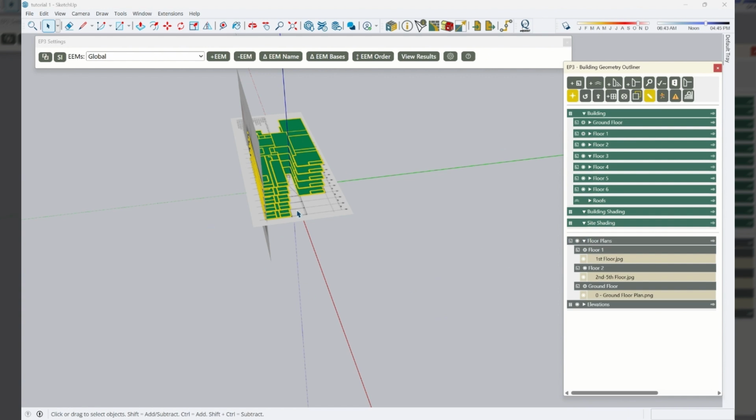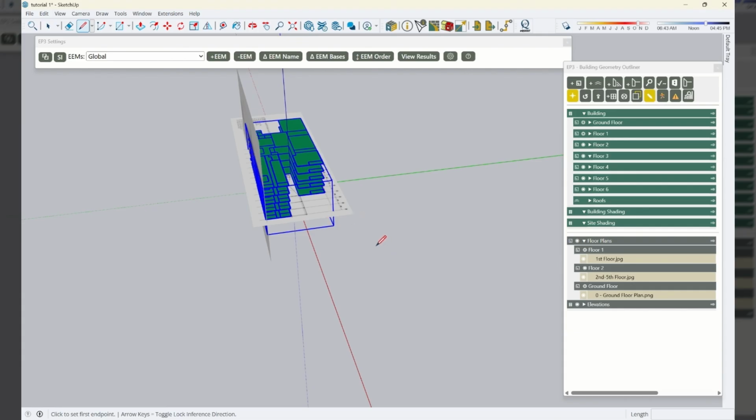If I want it to refocus on the geometry, I can either click in the geometry and then my L shortcut works. I can also click, so now my shortcut does not work. I can also click on the top bar here and it will focus it on the SketchUp space, and now my shortcut keys do work. Okay, so I'm going to hit Control S to save.